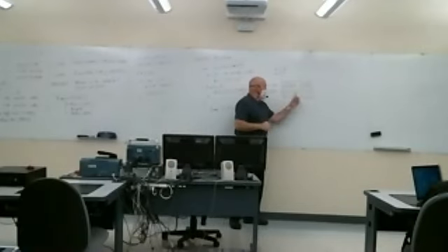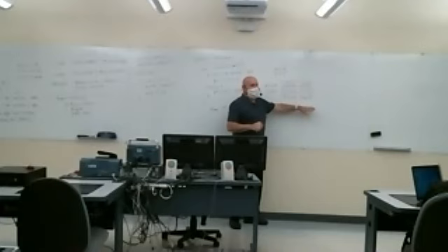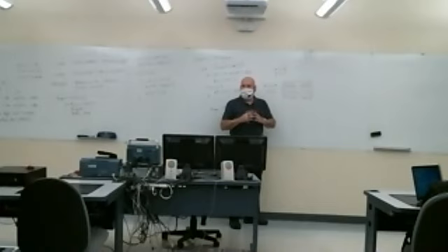Now, this thing is going to have 2 possible values, right? It depends on whether B2 is 0 or 1. If B2 is 0, what is this 8-bit result equal to? 0, right? If it's 1, what would the 8-bit result be? 4. There are only those 2 possible values when I do this ANDing.